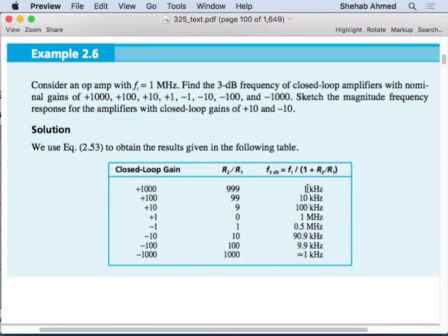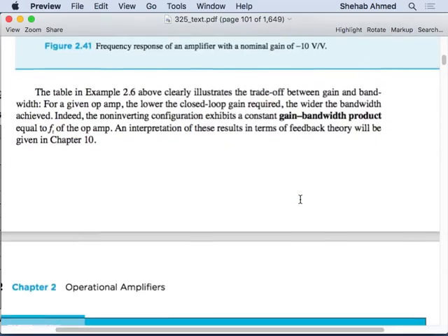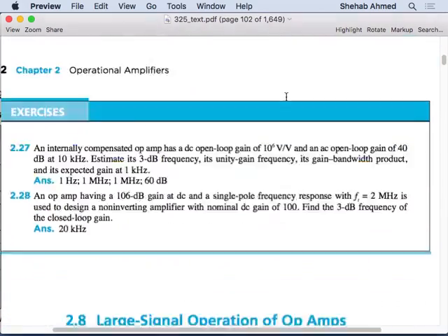And then they also substituted in the break frequency. They calculated the break frequency. They're telling us, look at this: when you look at a high gain, you're looking at small bandwidth. Low gain, you're looking at high bandwidth. So they're telling you that the gain bandwidth product for any op-amp circuit is a fixed value. Right? That's what they're telling you. So this is the reference to that.